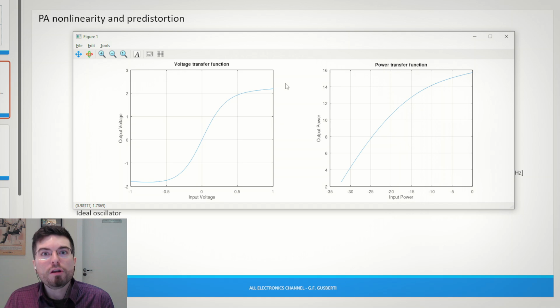It has the topology limitation, the maximum output power for that topology, for that matching network that's being used in the power amplifier, if it's a class E, a class F, a class D, a class A, a class B amplifier. And we also have nonlinear components inside the active device, like junction capacitances and thermal effects, that are changing the behavior of the amplifier in real time. All these effects in conjunction contribute to the limitations of the amplifier, to this non-linear behavior in the extremes of